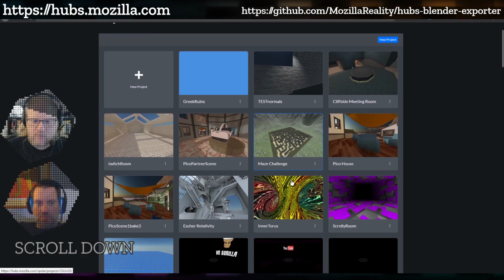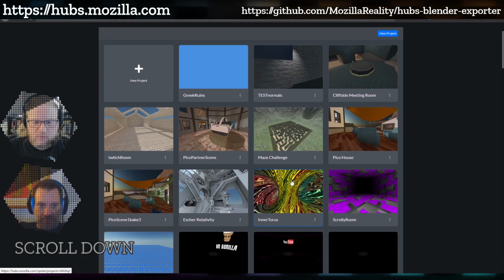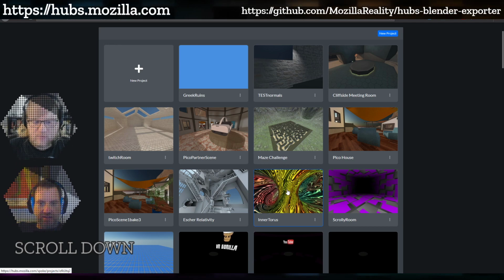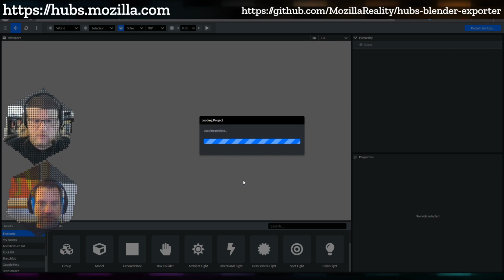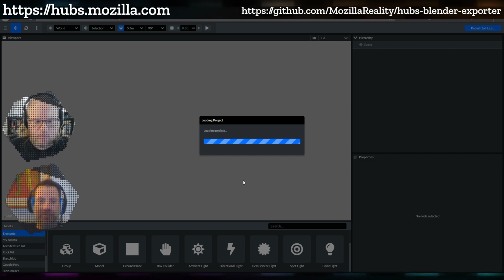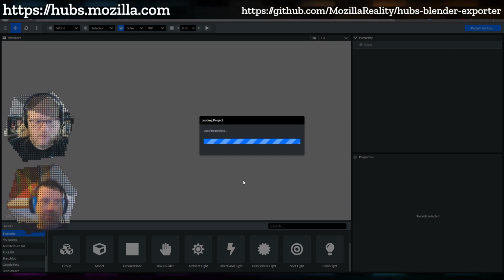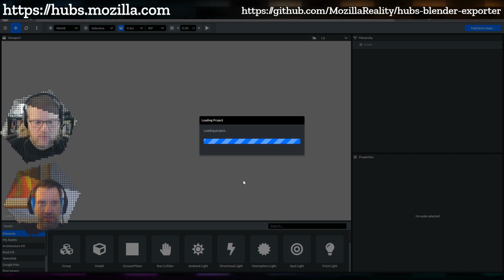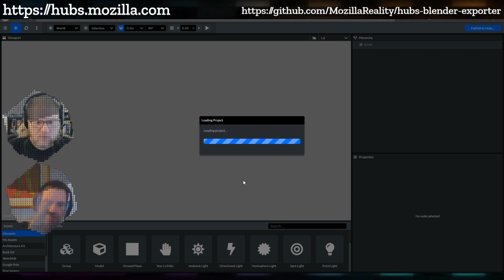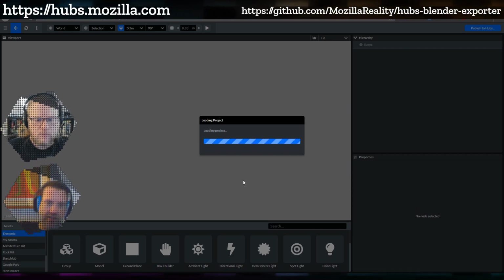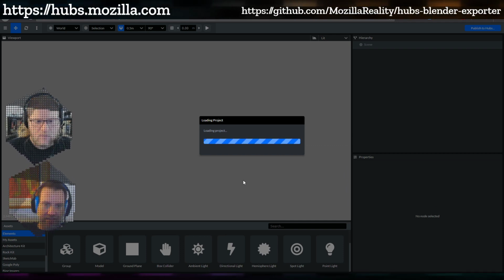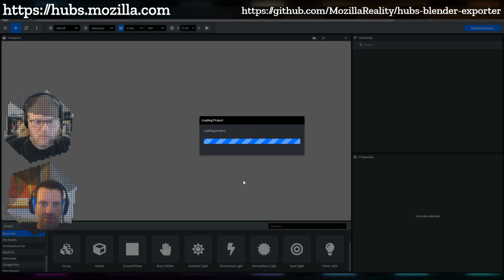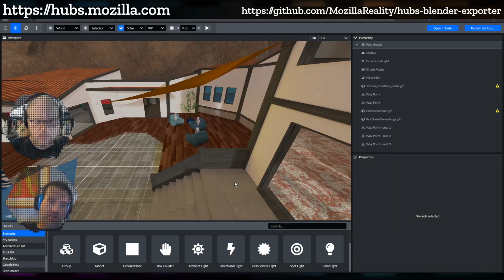When you get into more complex scenes, what I found is that in scenes like this, probably, like I said in the beginning, the biggest errors you run into happen to be with oblique angles, things that are not straight on the grid. And now that you know how the voxelization works under the hood, that gives you some insight into that. So plan accordingly or adjust accordingly.